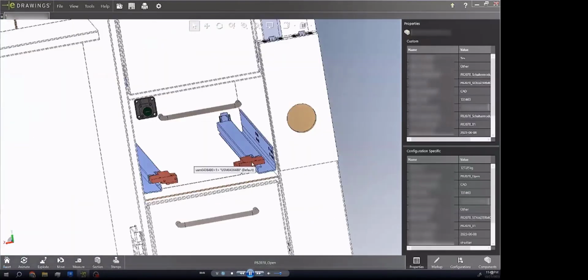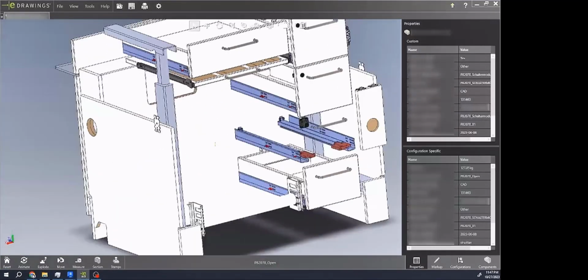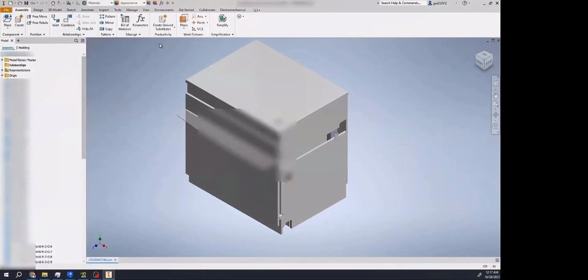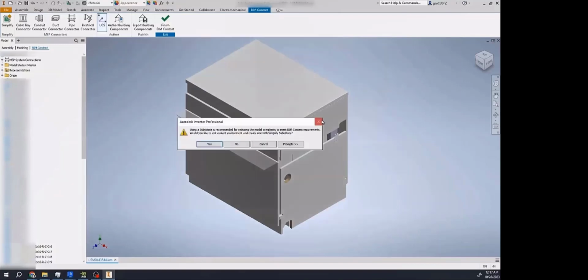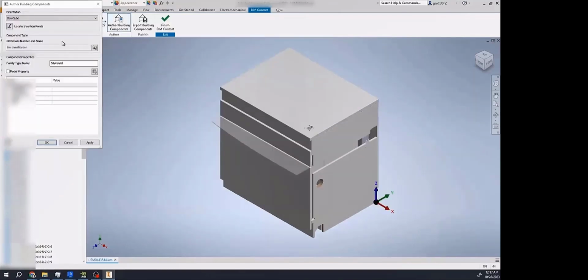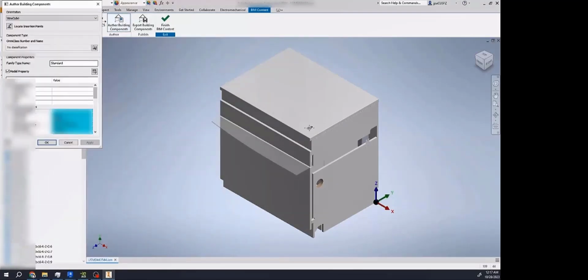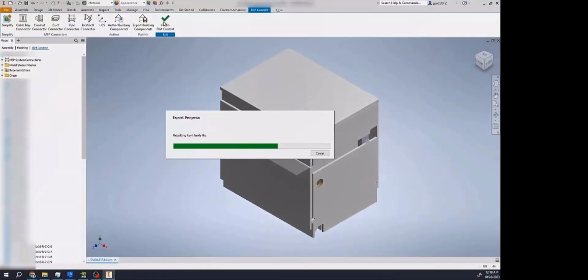So in this case, this is actually the SolidWorks model that was used for a whole Bill of Quantities, and I found the SolidWorks model can be very easily imported in Autodesk Inventor, and then Inventor has a good connection to different BIM applications. For instance, here we can set a local origin, and all these kinds of parameters we get from SolidWorks, we can convert into Inventor and then bring it to Revit. In this case, we don't need Rhino at all. We can just use the native tool from Inventor.